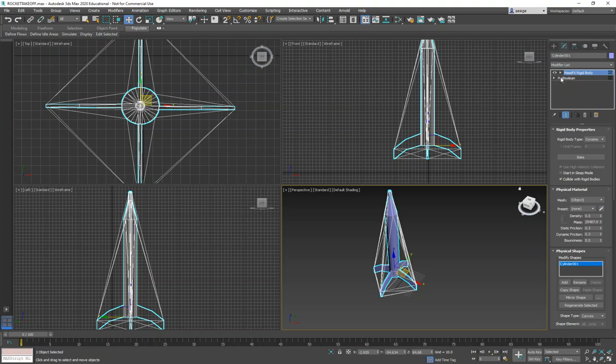Everything we did geometrically. And for MassFX, I'm just showing you by clicking on the arrow at the top right-hand corner that a number of things have been added automatically by just selecting the MassFX toolbar. Basically, the MassFX toolbar added initial velocity, initial speed, center of mass, and the mass transform. For example, if you want to know where the center of mass of the rocket is, click on it. You'll see the arrows about 1/3 from the bottom up.